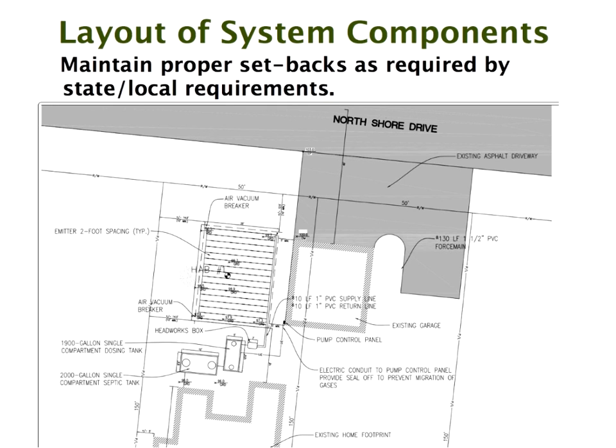So for instance, obviously it's important to polish that effluent so that it removes suspended solids, and so without the advanced treatment or secondary treatment, what we required was 150% of the storage capacity or tank size prior to pumping